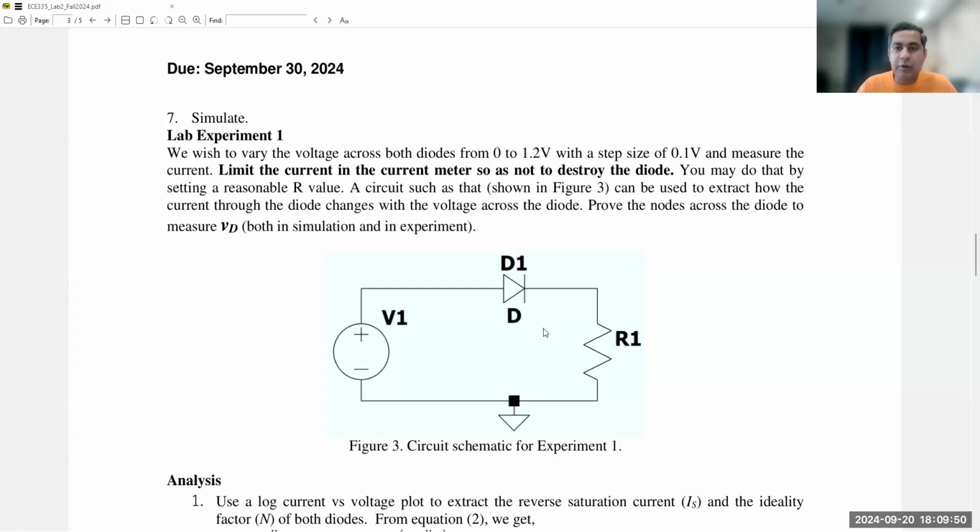To make sure that your diode is safe and your circuit is safe, look through the device datasheet that you can get online. You just have to search with the diode name, which is in this case 1N4004. So if you just search 1N4004 datasheet, then you can get the datasheet for this diode, where it usually mentions the value for forward bias current. You can see the maximum current that you can flow through these diodes.